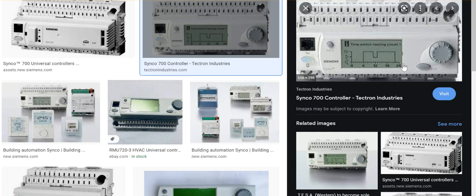But later, if you want to have it on a PC, you can use the ETS database of this device. You can use the ETS software on a PC, configure it in ETS and download it. So we have different types of configuration. During this course, we only focus on S-mode devices. For easy mode devices, some manufacturers make them, like Siemens, like Gewiss from Italy, as I remember, like Busch-Jaeger, I think, and similar. And Hager, yeah, they have the easy mode devices.